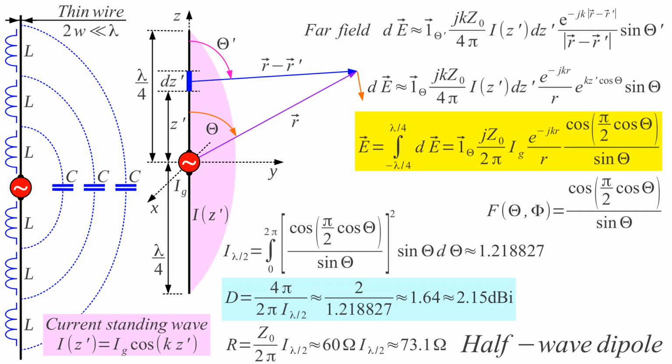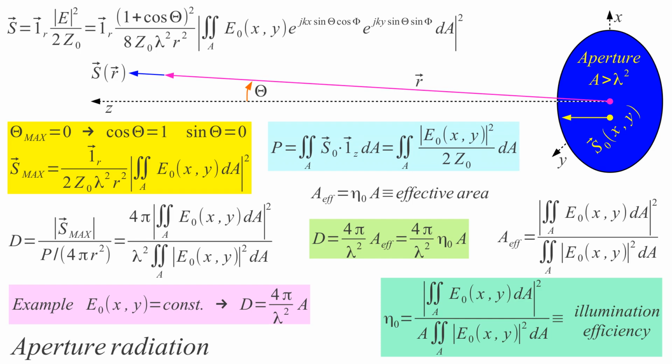Now, dipoles are useful to build many antennas, but there are still antennas that are very difficult to handle in this way, like an aperture. What is an aperture? The area of this aperture may be covered with dipoles. These dipoles have their feed structure, their wires feeding them, so it's very complex to get the current distribution over an aperture covered with dipoles. It could be covered also with something else.